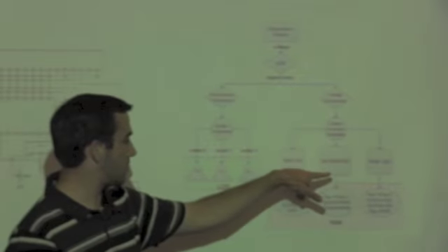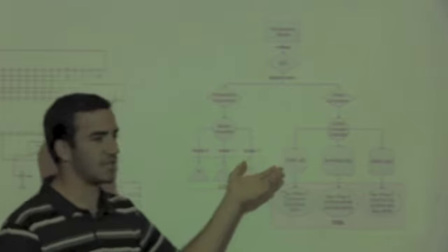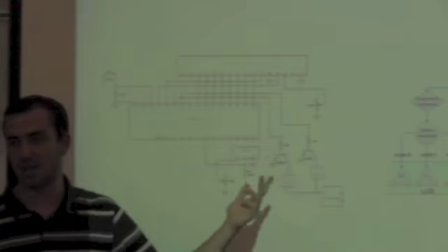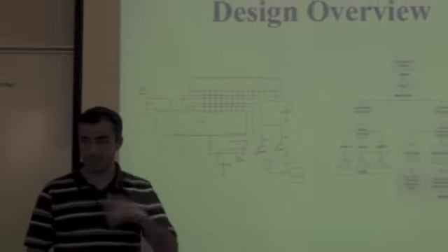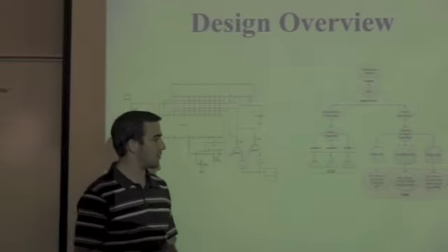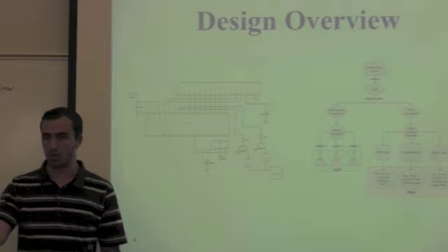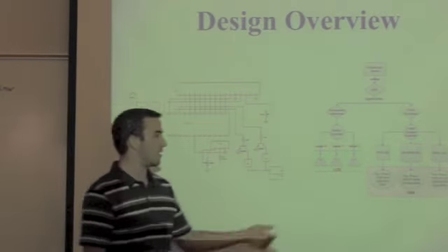RPM is a variable that stands for the output compare register, and we chose for values under 60 to be negated to 0 because friction wouldn't allow it to run under that, and it wouldn't be as beneficial as you would think to go over 60 and then drop it down in order to have it run.